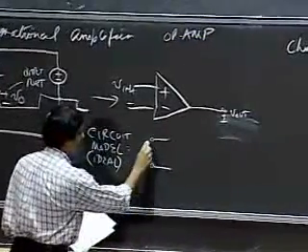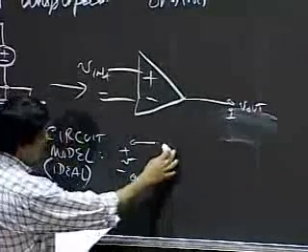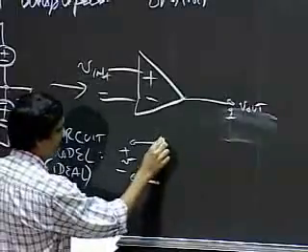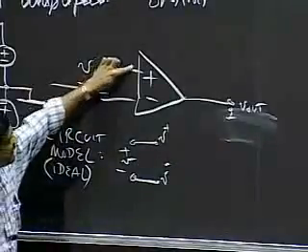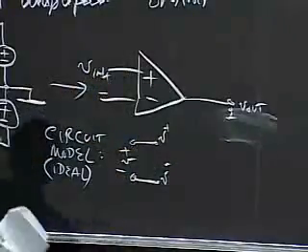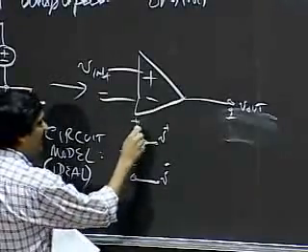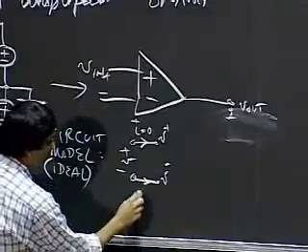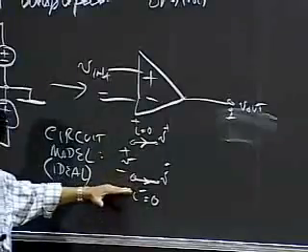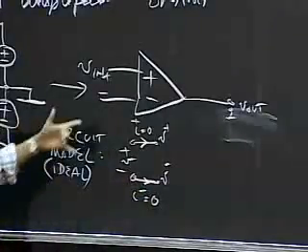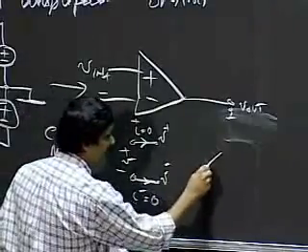And in terms of analyzing how this behaves in a circuit, I'm going to show you this abstract circuit that looks as follows. So some input V is applied at these two terminals here. And this terminal is called my V plus terminal. And this is called my V minus terminal. So this corresponds to these two terminals. I'm telling you that the current going in is going to be 0. So I plus is going to be 0. And I minus is going to be 0. So I plus is the current in here, and I minus is the current into the V minus terminal, and both these currents are going to be 0 in this device here.